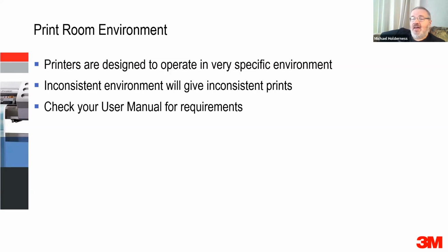One of the best examples of that was a company up in the islands. They bought a second-hand printer off Trade Me in New Zealand, and they got it shipped up to the islands. And because they didn't know any better, because it was a second-hand printer off Trade Me, they put it into a garage in the islands, and it was 30-something degrees in there during the day and very high humidity. They never actually got the printer working because by the time they got it out and set up, all of the heads were blocked because of the high temperatures and the high humidity.